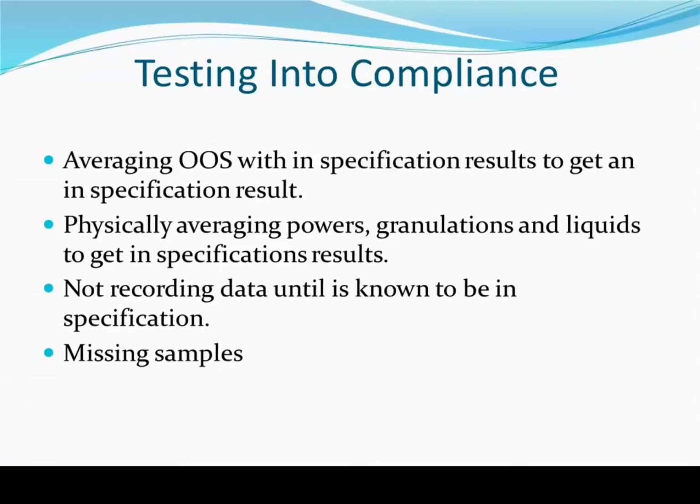The vacuum will pull the water down over the filter paper. You'll do a few rinses with WFI, and then that filter paper will be removed and placed on an agar plate and incubated for about 3 to 5 days. In this case, we weren't seeing that telltale sign that the vacuum was applied, and then we started to find samples in the trash that were unopened.